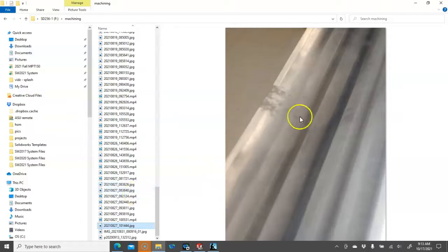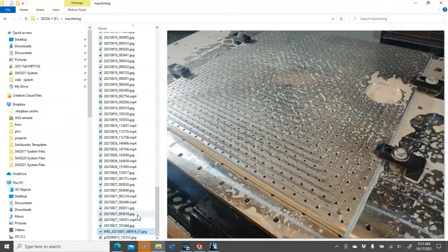This was where that 5 thousandths drop, but those little, we'd call it a butter coat, the raw material of the aluminum, that little bit of scaling is going to have to be acceptable to not take any more material and build out the other piece.